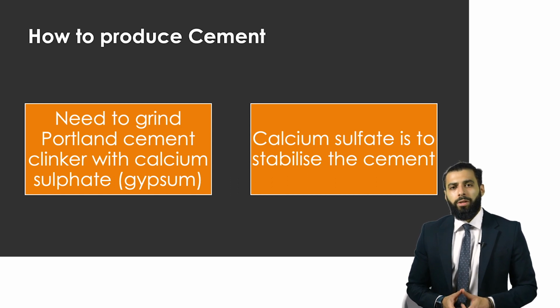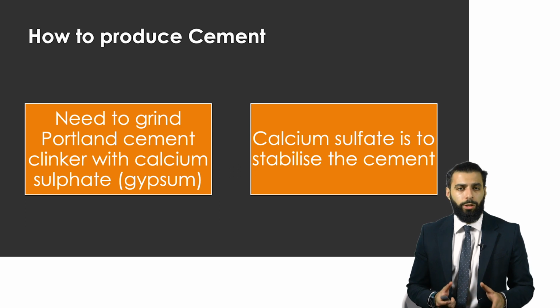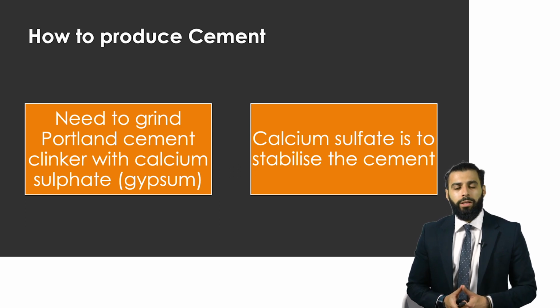In terms of the requirement for gypsum, well, the Australian standards do specify a certain limit in terms of how much percentage of gypsum you can mix with your cement clinker. But as we will see in a different video, gypsum is important in the control of the hydration of C3A, and thus it avoids flash setting from taking place in your concrete mix.